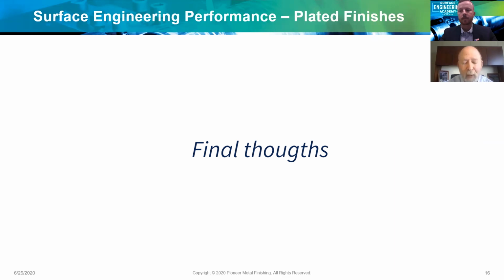You, for example, might feel that you need wear resistance and you go ahead and harden your material, and ultimately that required more work for the plater versus just getting a hard plating on the surface of the part. So it's just important that if you have the ability to choose the plating process, get your plater involved as early as possible in the engineering phase.